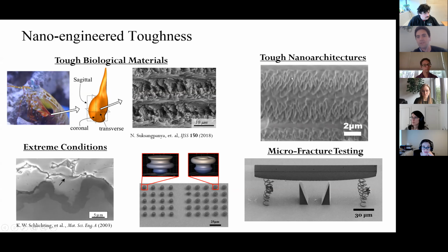The lines that are sticking out are the individual line passes from the Nanoscribe, but we're doing that to mimic some of the natural gradient and porosity in tough biological materials. So you can have pores and you can have flaws the same way as a normal 3D printing process, but you have a lot more control over where those exist, which we're actually trying to use intelligently to see if we can engineer toughness.